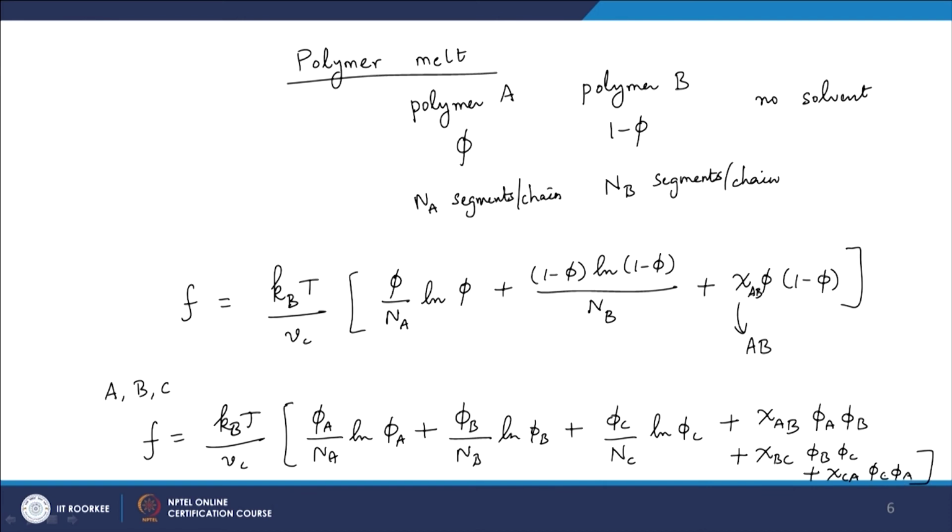So this is the benefit of the lattice model, that it provides us an easy way to construct the Helmholtz free energy density of my polymer systems, and using that, by the math that we have done, we can go ahead and try to find the binodals, spinodals and critical point, and we can actually draw a phase diagram of the sort that we have discussed here. So I will provide some examples in the course that you can work through and try to apply the same concepts that we have just used here for somewhat different types of polymer systems. So with that I conclude. Thank you.